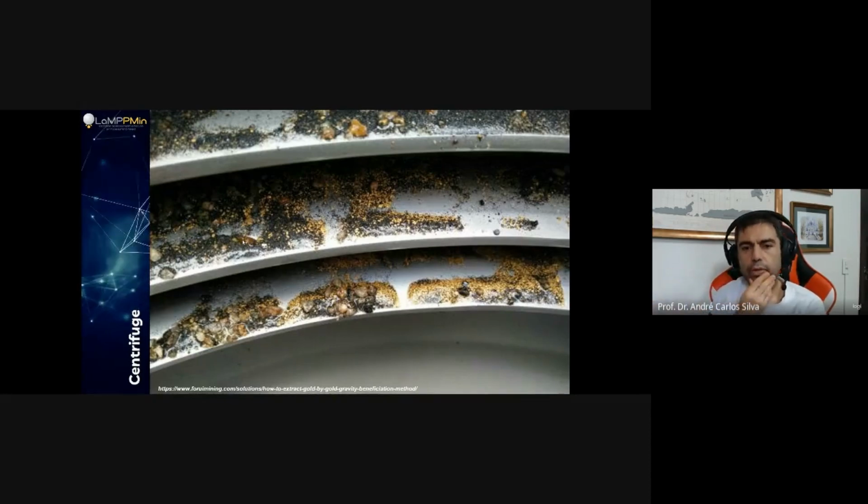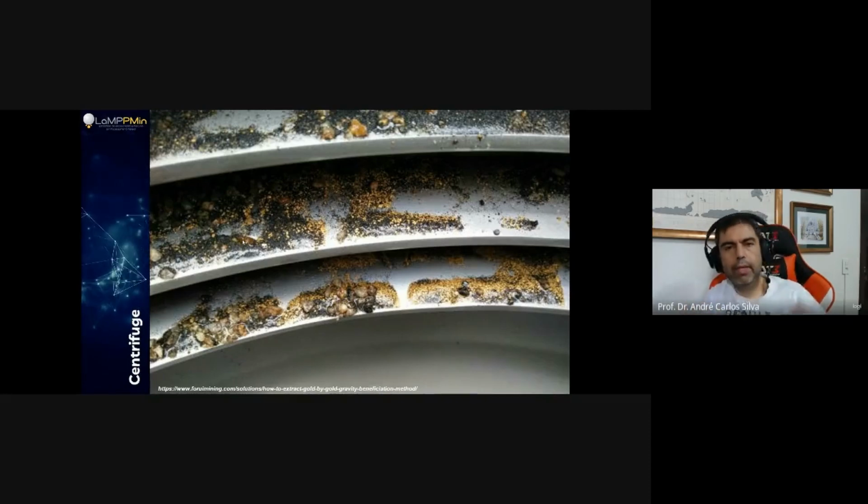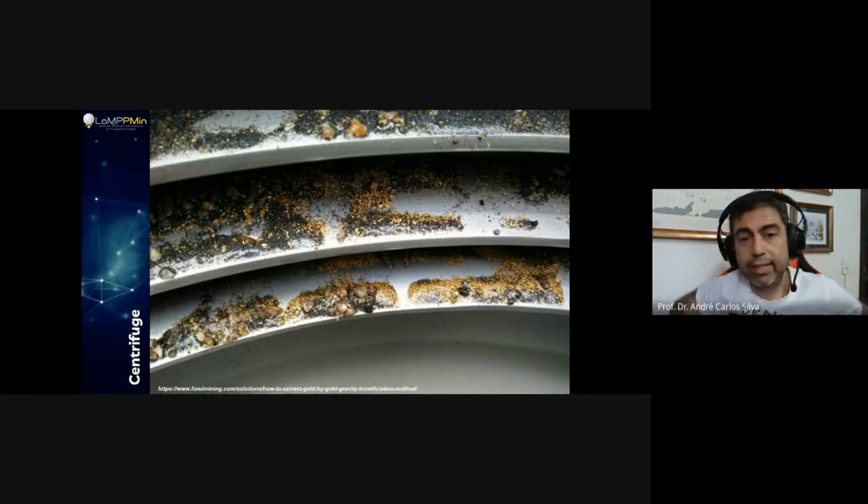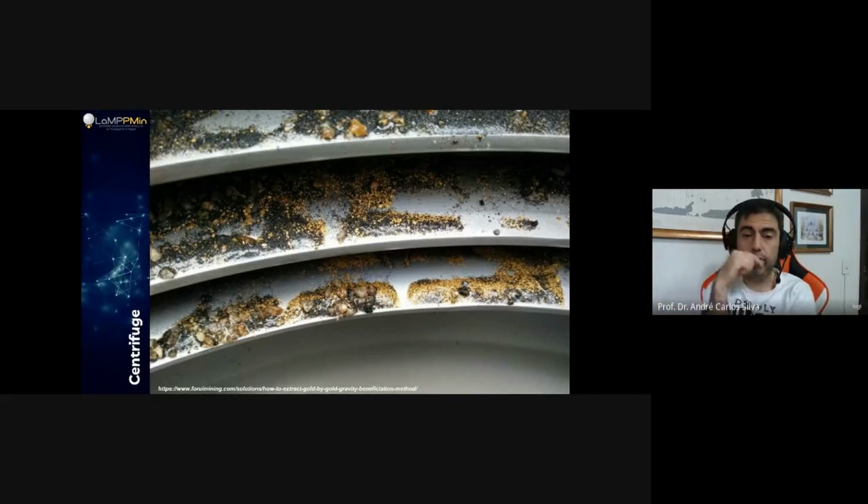If you take a look at the gold circuit flow sheet, you're going to see that in the closed circuit that you have with the milling, if you don't put any kind of concentration in your circulating load, what is going to happen is the gold is going to be retained in that circuit. Why? Because the gold goes into the mill. You definitely can't break gold in a ball mill. You're only going to produce something like cigarettes of gold, and these gold particles go straight to the hydrocyclone. And the hydrocyclone is going to look at it and say, "Oh, that's heavy." Okay, if that's heavy, it's because it's big. Okay, so it's a coarse particle. It goes down to my underflow, and the underflow goes back to the mill.